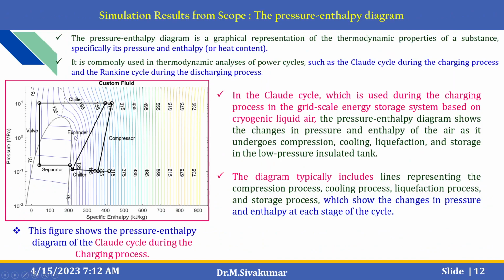Then finally, the pressure enthalpy diagram is also available in the simulation results, Simscape logging. The pressure enthalpy diagram, as we already discussed, is a graphical representation of thermodynamic properties of a substance, specifically pressure and enthalpy. This diagram shows the Claude cycle during the charging process. What is a Claude cycle? It is used during the charging process in grid scale energy storage based on cryogenic liquid air.